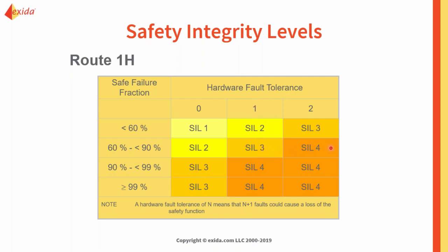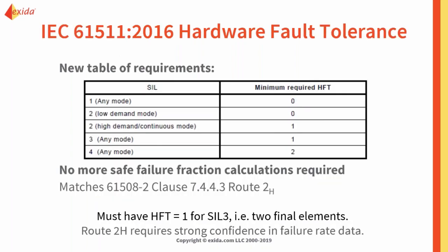And we would not be doing this in the process industry, but if you were maybe in rail or nuclear and your requirements said for that safety system, the requirements need to be a SIL 4, you would then look at this table and say, with the equipment I have, I would need at least 2 extra sets of equipment to do that same job.